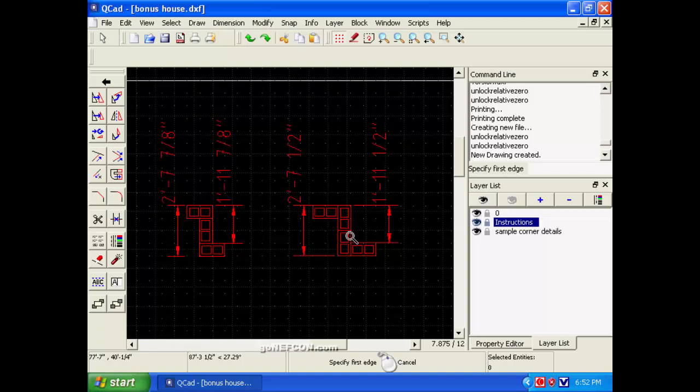So what we have here is that the bigger number has to prevail, because you can't stack this longer stack of blocks in the same place this shorter stack of blocks lives. So you've got to take the longer of the two, and that's this one. So what that means is that when your wall does an outcrop transition, the outside edge of the wall transitions 1 foot 11 7/8 inches. And that's very important information.